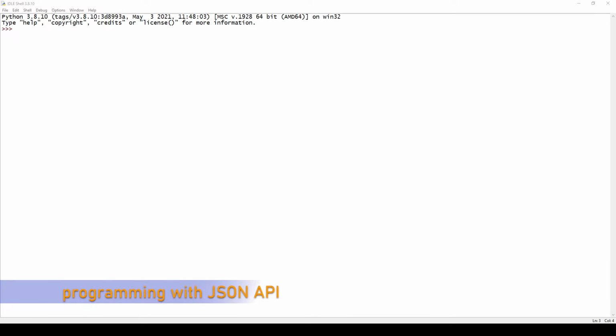Let's show how to use the JSON API with Python using the Python command line. First, import the modules we need. The JSON module is part of Python. We provide the sensors module. Open the connection to the LD100 tool server. We're using the one running on our local machine. We could also access a server running on a remote system. Let's ask for a sensor reading.